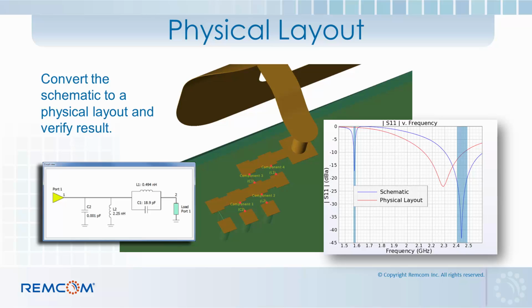If you look at the schematic, you can see that the load, for example, is just treated as an impedance block. But if we look at the physical layout, we can see that the antenna is actually near the matching network. And if we look at the fields, we're going to see that there is quite a strong interaction between the antenna and the matching network. And Optenni is not able to account for that. And so that's why we're seeing the difference between what the XFdtd simulation would generate and what the schematic would generate. So again, let's go back to the software and have a look.